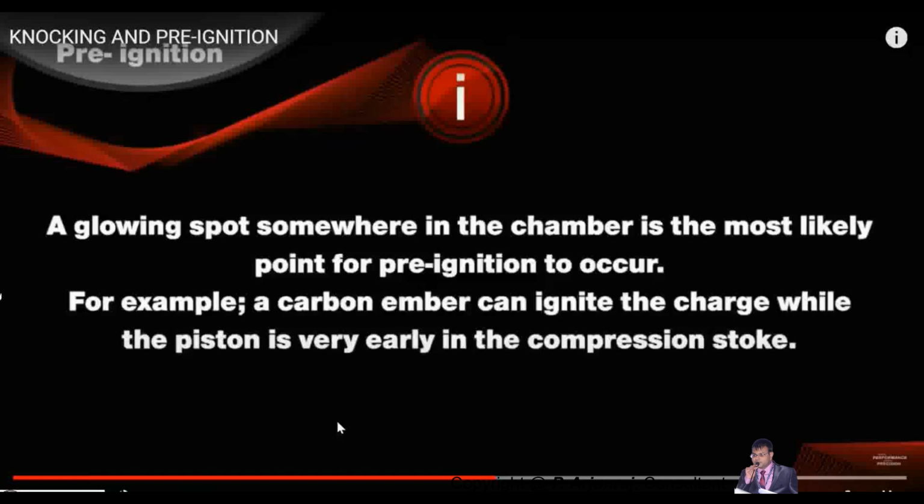When the flame speed is higher and the time taken is lesser, you give a very minimum chance for the auto ignition or self ignition to take place. Even by increasing the flame speed, you can reduce the knocking effect in an engine.